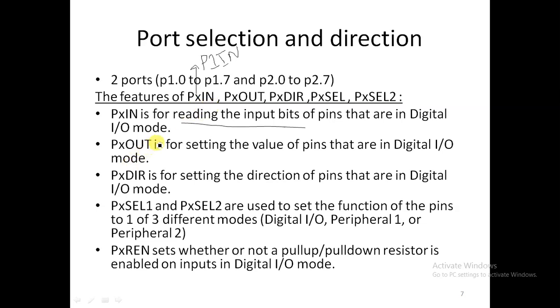Next, let us see the general meaning of these instructions. PxOUT means we are going to send the value through these pins to the outside of the LaunchPad, that is, IO interfacing, to any external device. Next, PxDIR means we give the direction to the pin: which pins should be taken into consideration to send data and receive data.